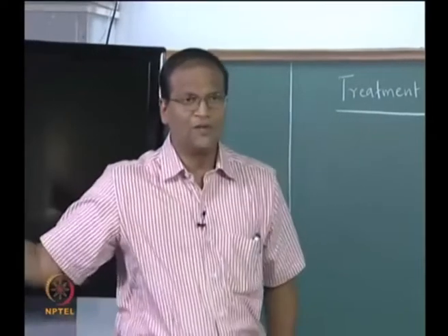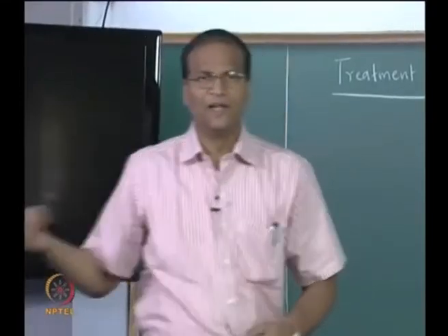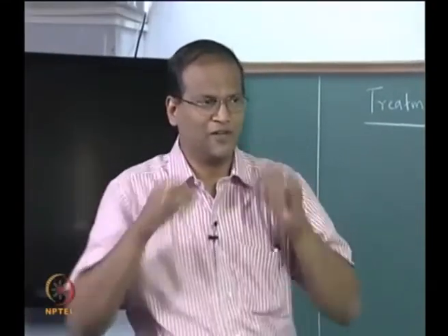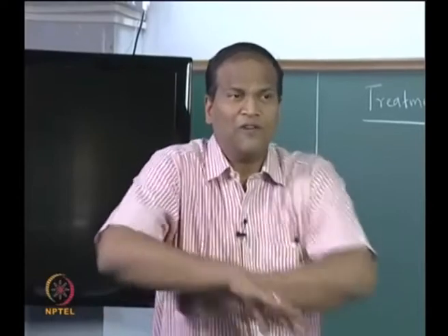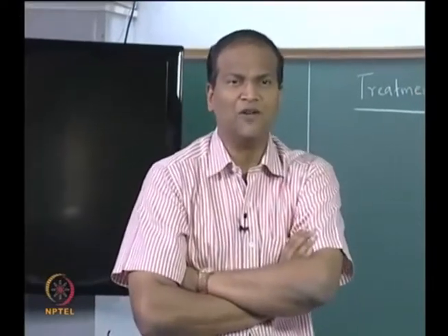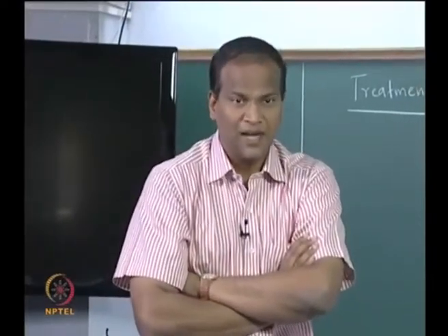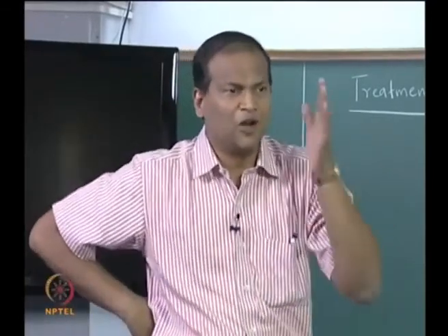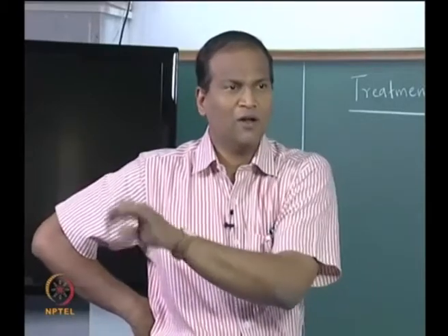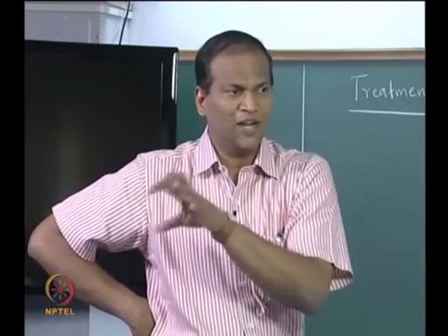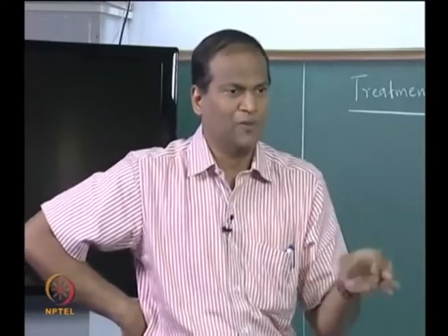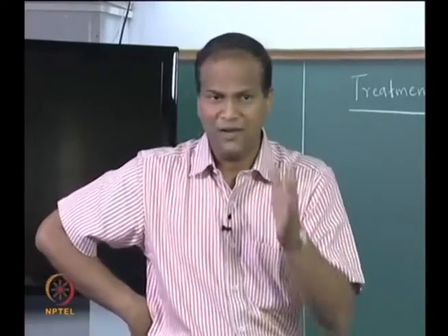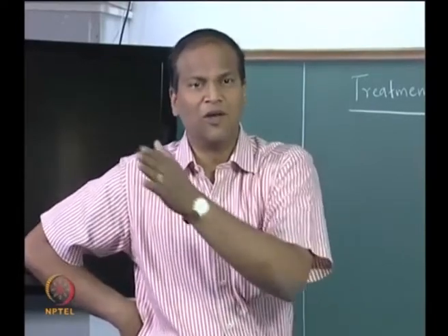So Deepak is coming out with some answers, he is saying that we have to use the f function chart. If you have to use the f function chart, that means you have to use the f function charts for different ranges of the interval. Are you getting the point? If lambda is from 0 to infinity, if there is a value of epsilon 1 for 0 to 3 micrometer, then you will use some f function chart and find out what is the total amount of radiation in terms of sigma T to the power of 4, and then 4 micrometer to 7 micrometer, 7 micrometer to 9 micrometer, whatever up to infinity.